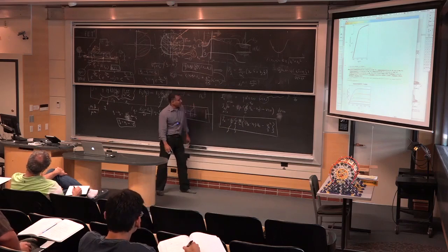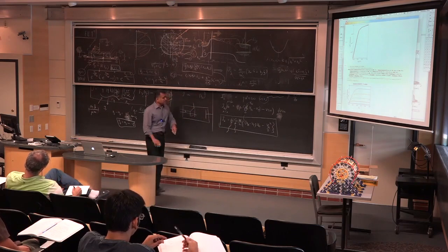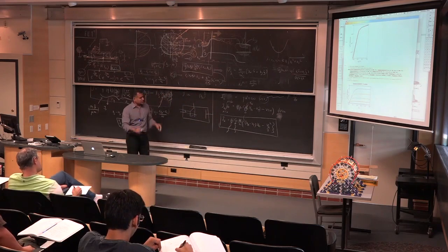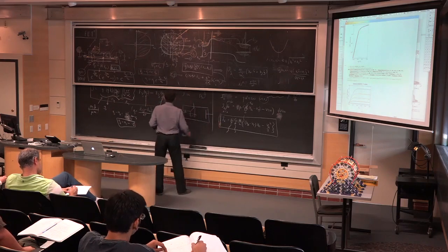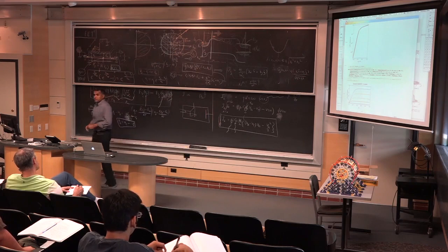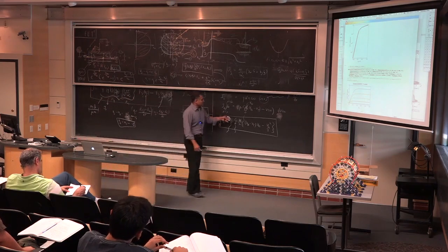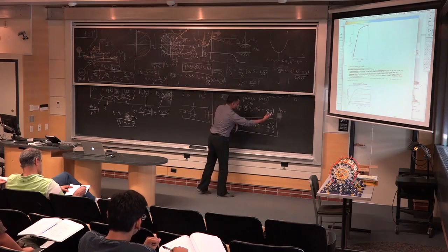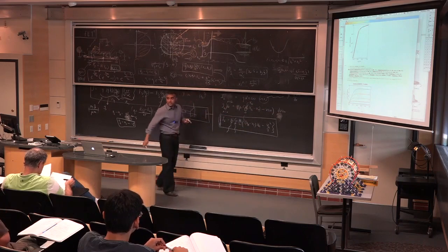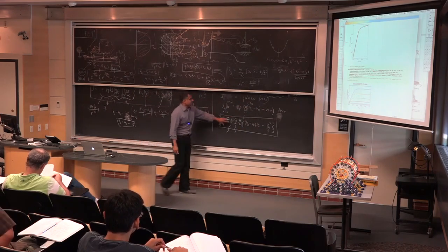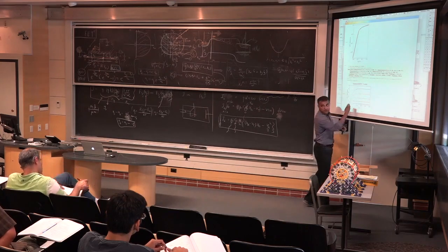So that's the picture. And if you plot this, there are some other things. It doesn't explain the off state. For that, people have used surface potentials and other things like that. So this is the classical picture of a transistor. That's the quantum picture of the transistor. Interestingly, when you plot it, there are a couple of things I'm not mentioning as far as saturation, such as the surface potential, but they will look the same if you plot them in the end. So this picture covers the triode region, or this part of the curve, pretty well.